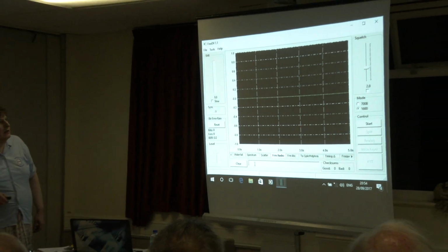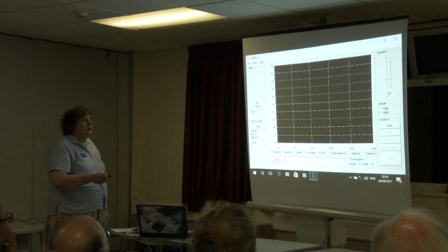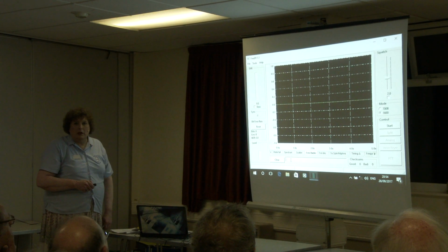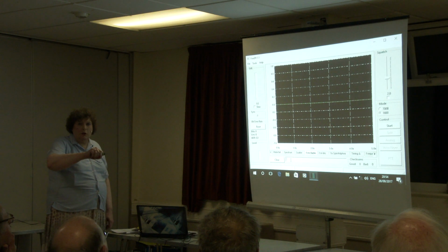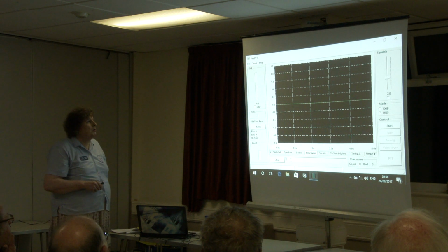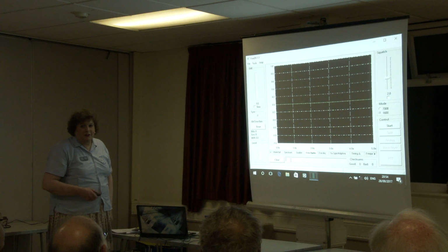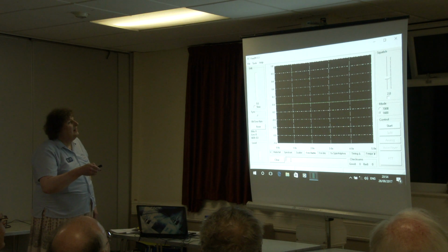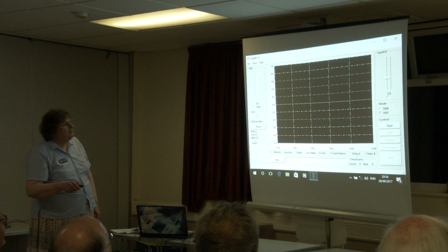I'm going to come around here, it's easier. Squelch settings can be done here. Now this is digital squelch in preference to your analog squelch, so you can turn your squelch open on your radio. You don't need to put squelch on. I know some of you don't believe in it because you like to listen to all that racket. So it's actually quite useful at times.